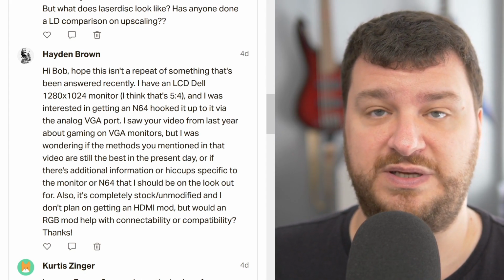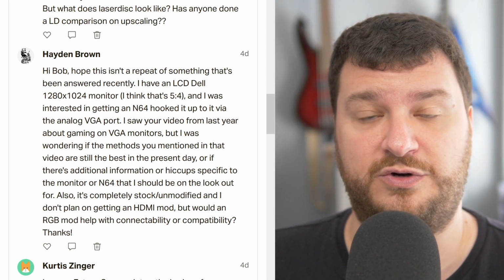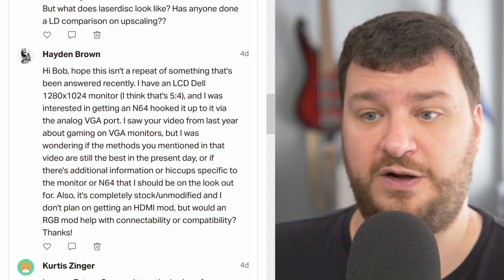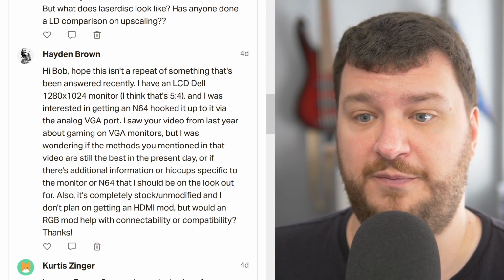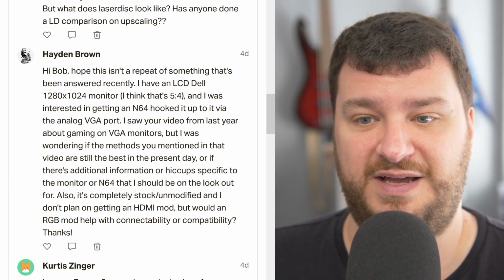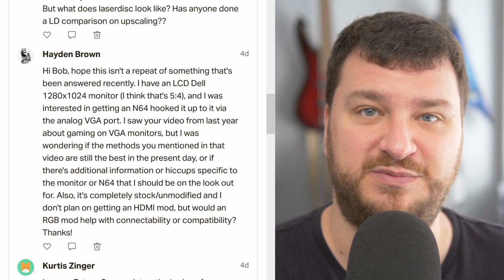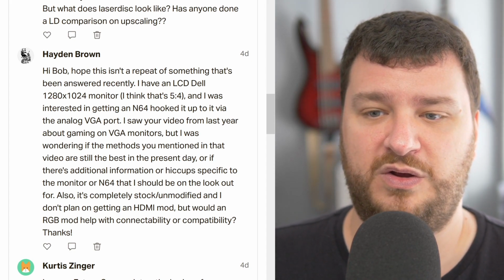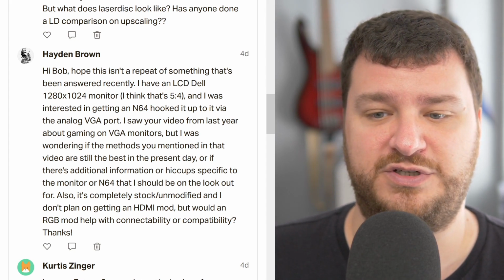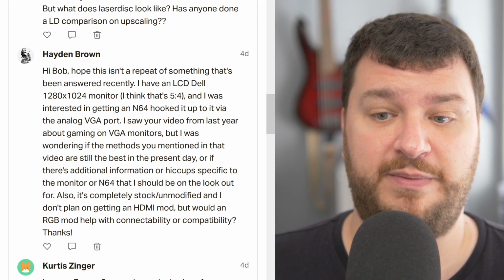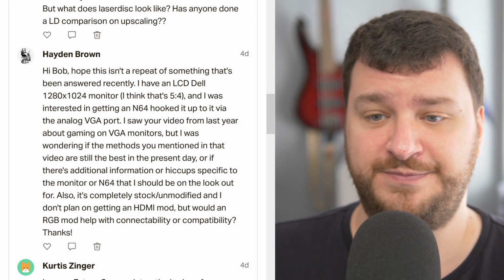So you could either get a Core U transcoder and go from S-Video to Component and then go into either one of those, or you could RGB mod your console and use HD RetroVision cables and the GBS control, or I guess if you modded it for SCART, that'll work too. But all of those solutions are great. They're just more complicated.